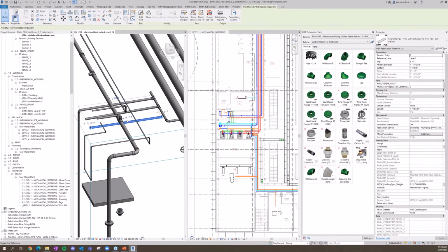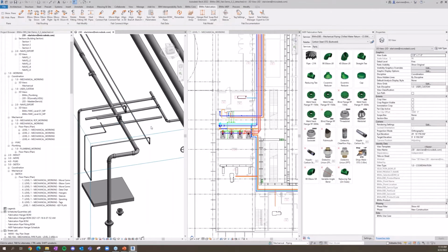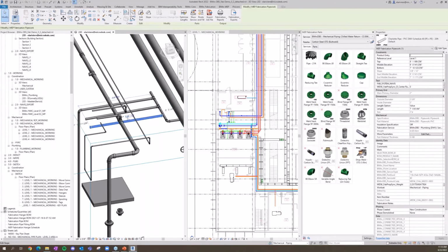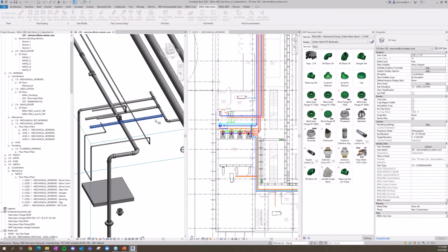And if we run into a scenario where I've got no slope, but it needs a slope, I can use align branch plus to inherit that slope as I am doing it. So there I go. I've also got the slope inherited now.